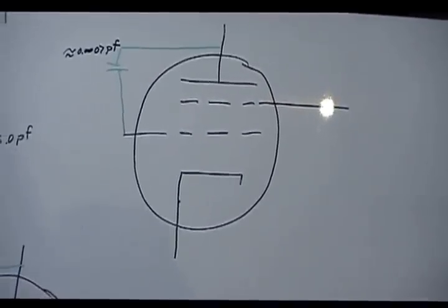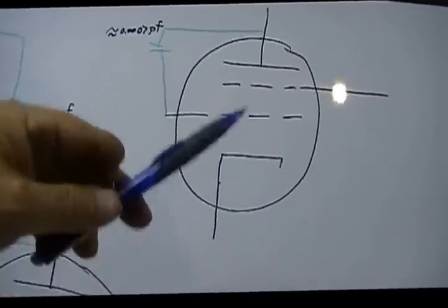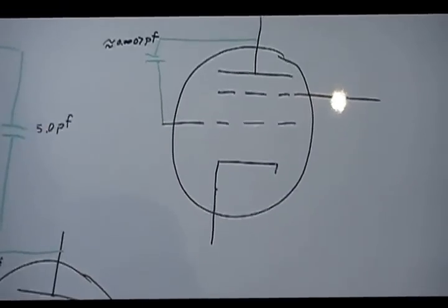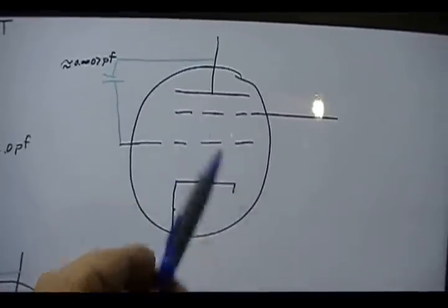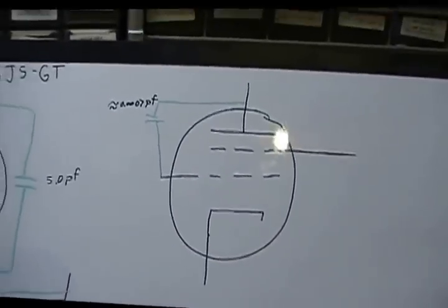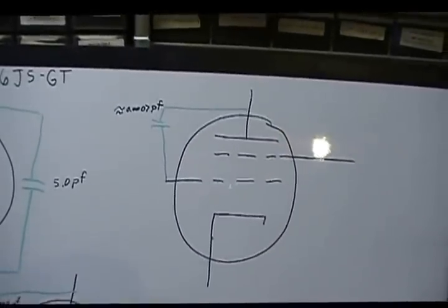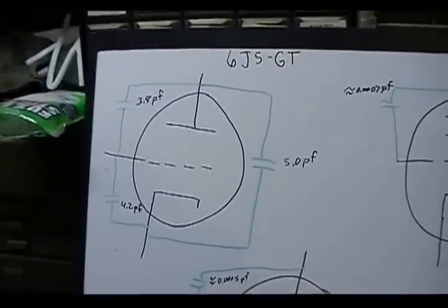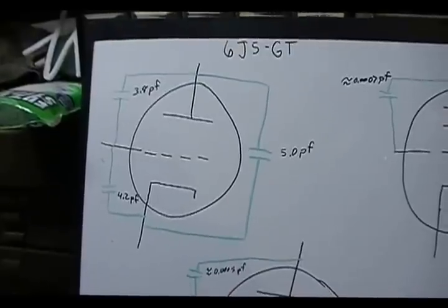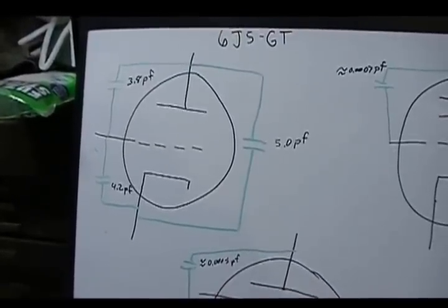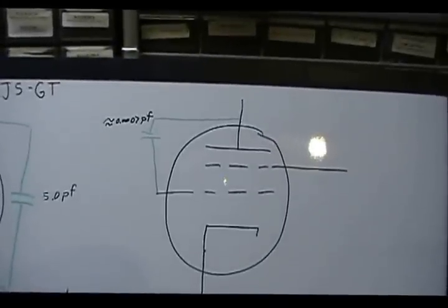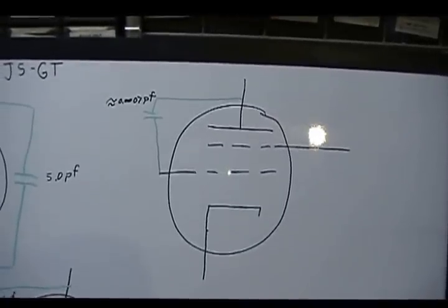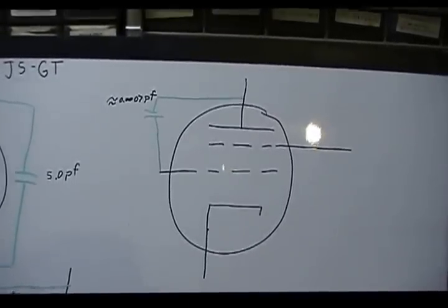Now, one of the other advantages by reducing this, and a few other dynamics that actually happen in the tube by placement of a screen grid, the mu went way up. Remember I said on the Triode we're looking at a high mu tube upwards around 100, not much above that. These can easily hit 600 or even a little above.